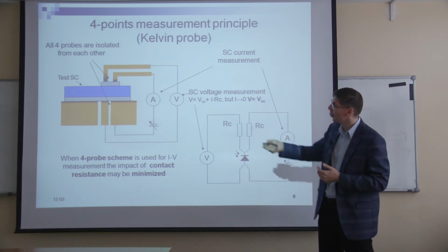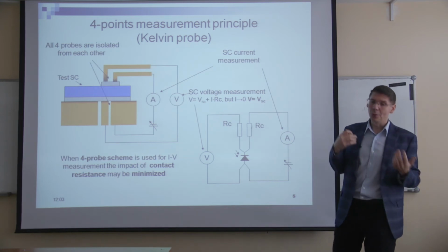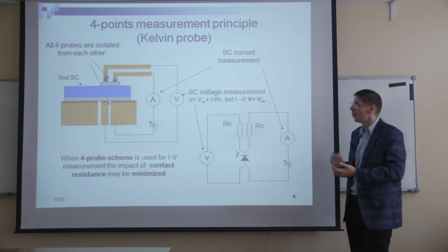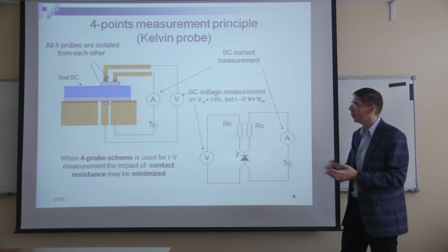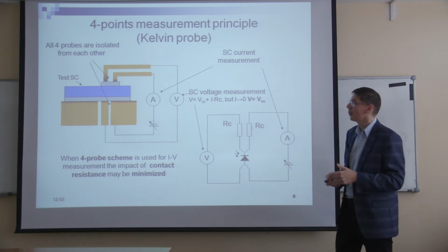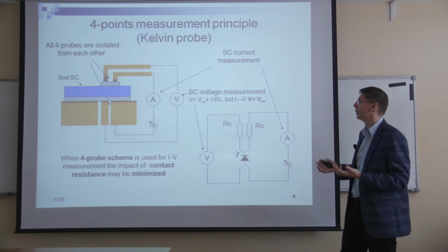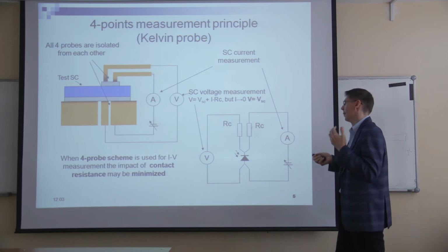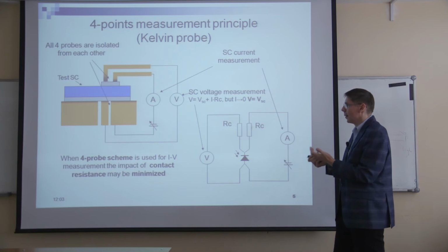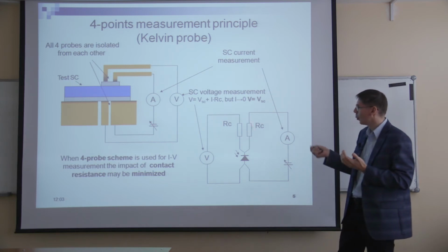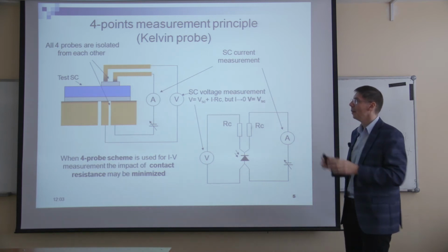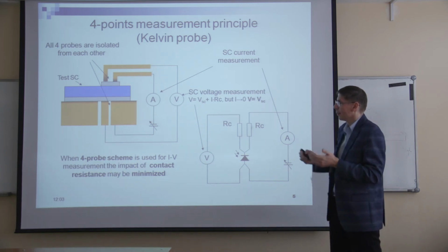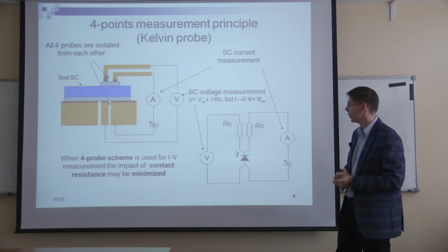So concerning the correct IV curve measurement, first of all, it's quite convenient to use the 4 terminal to save your time, because you can check if there is no problem with the contacts first. And the second, which is really important, it's the only way to avoid any problem of the contact resistance. I mean, in this case, you can measure without any doubt about contact resistance.